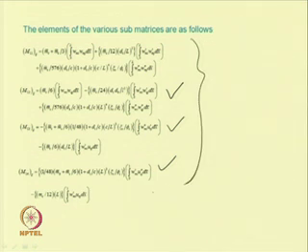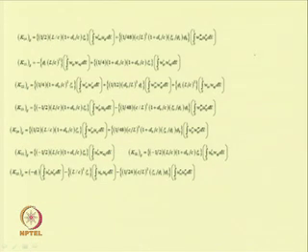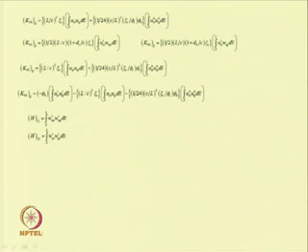So, one can find this mass matrix using these expressions which are obtained by using the method of multiple scales. These are up to M44. Similarly, one can find k11, k12, k21, k22, then up to k44. So, one can find this mass matrix and stiffness matrix, and also the load vector.